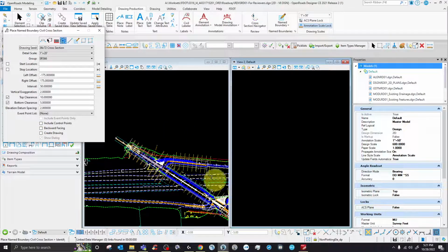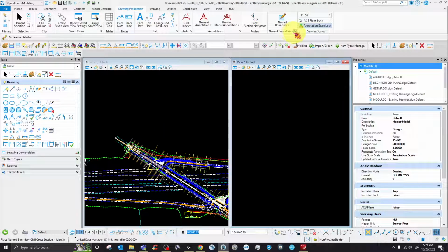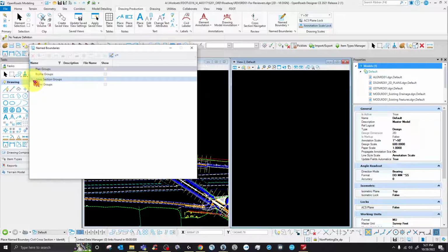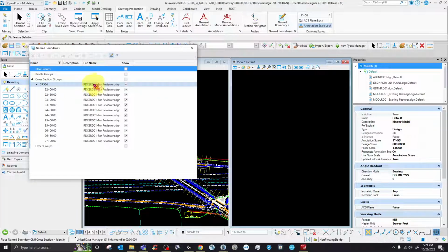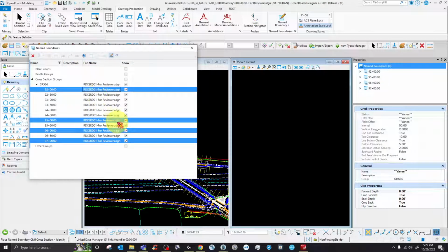After you cut them, you click again here and go to those cross sections that you have here, select all of them, and you can put them into one sheet or two sheets or whatever. Because if I select these and press create, for example, if I just want these and I want to create one, it will create a different one for me, and it's gonna take the same cross sections and you can see them here.